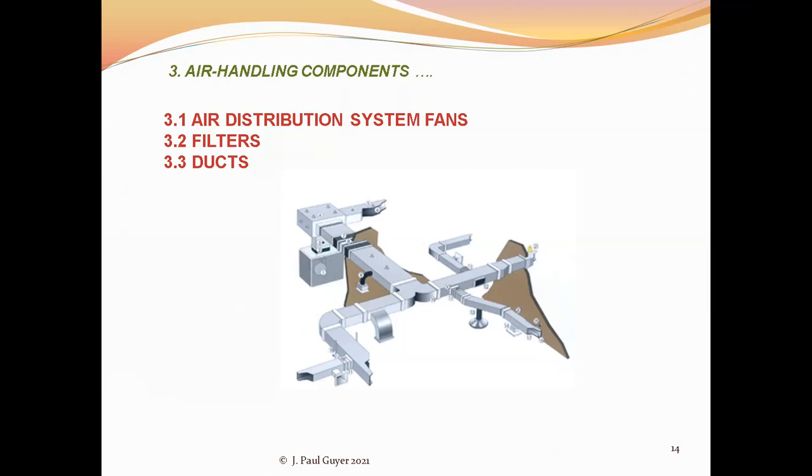And the filters clean the air, and they are there basically for air quality purposes, focused on occupant health and safety, and they are intended to, in addition to filtering out particulate matter, dust, this sort of thing, they inhibit to a degree bacteria and mold growth, and they keep coil surfaces clean, which is important as far as the efficiency of heat exchangers is concerned.